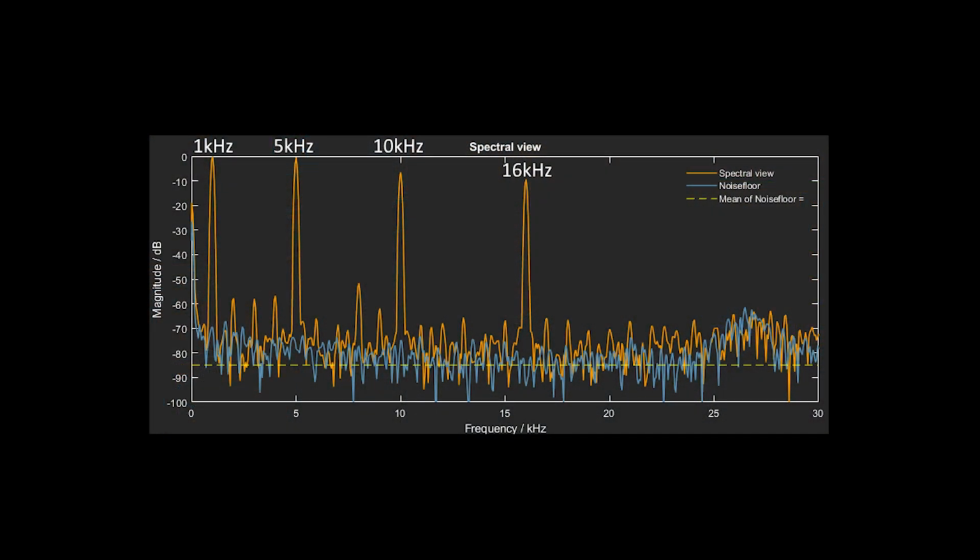In the end, the PDM itself has a signal-to-noise ratio of around 85 dB, resulting in an effective 14-bit DAC, but should still be more than sufficient for most applications. Alternatively, a small SPDIF converter could be used. The unbeatable thing of an FPGA is that all the individual logic parts can be recombined, exchanged or removed with little effort, and that the whole system processes the audio signals in real time.